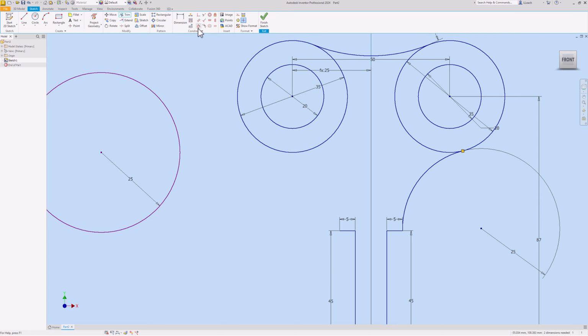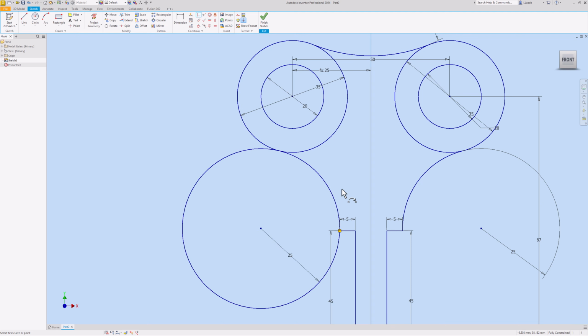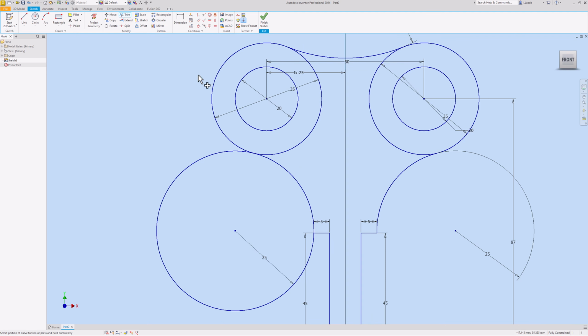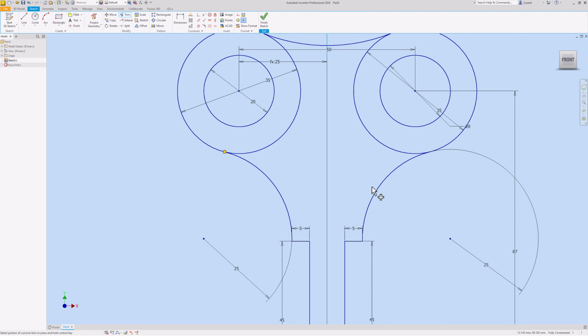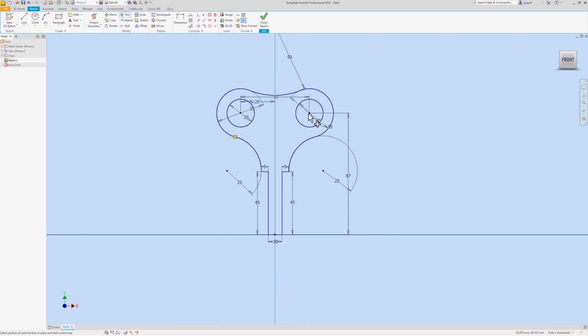So I want to click on my tangent, click this circle, click this outer circle, click on coincident, click the end of this line, click this circle, and then we can use the trim. We can trim that part off, we don't need it. Then I can trim out this here as well, trim out this here as well. We are fully constrained, so that's the outer shape of our ET looking head thing. And then I'm going to go to finish my sketch.